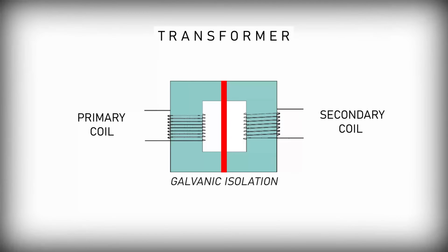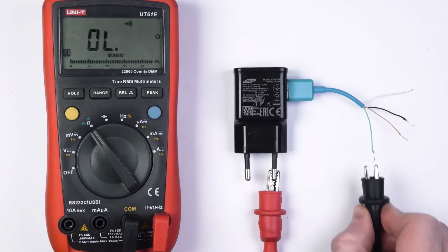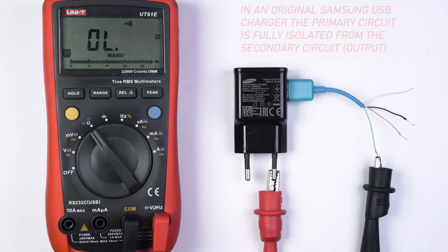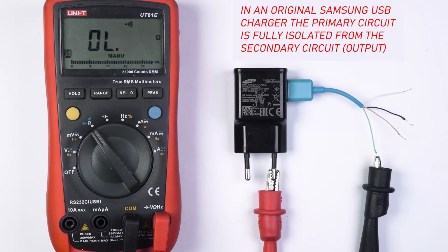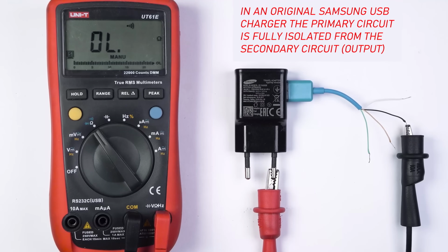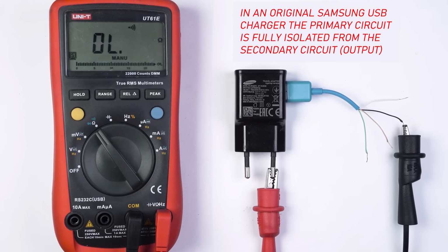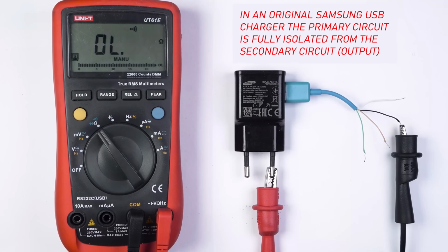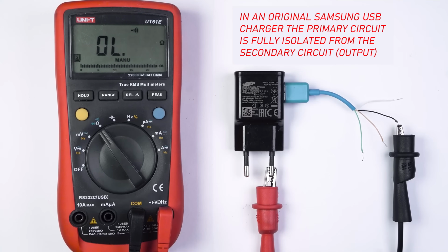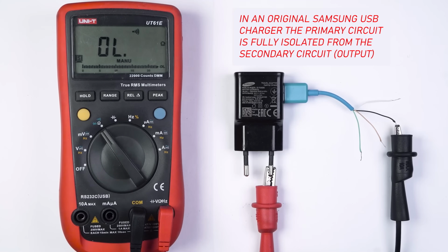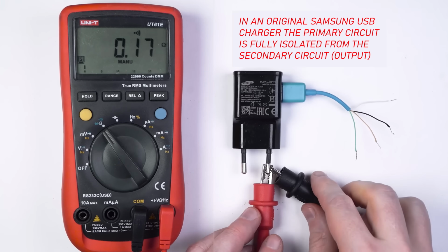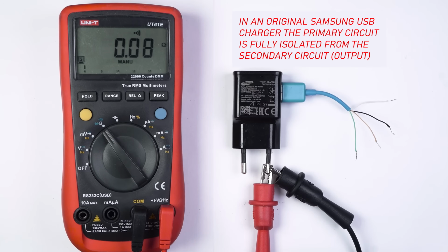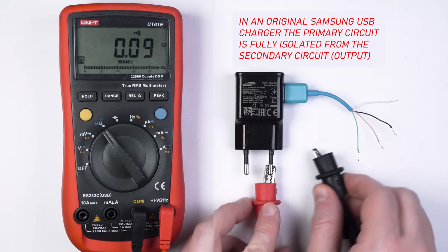So anyone who uses, say, a USB charger does not have the slightest chance of being electrocuted by simultaneously touching the USB cable and, for example, a radiator heater, since there is no circuit between the mains plug and the output connector of the USB charger, which, as you can see, can be easily verified with a multimeter. If the multimeter detects a circuit in your case, your charger must go directly to the garbage bin. It's dangerous to use it.